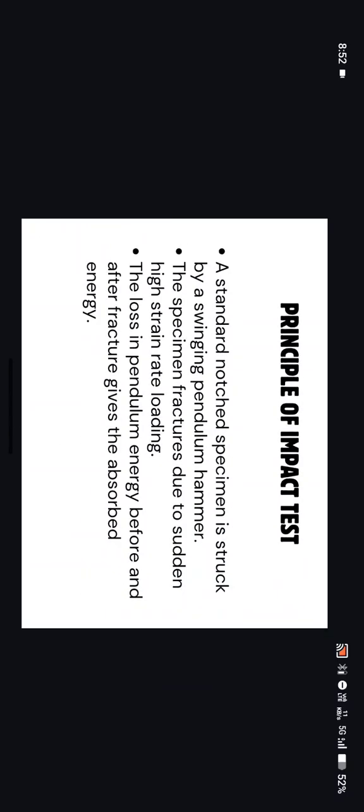Principle of impact testing. A standard notched specimen is struck by a swinging pendulum hammer. The specimen fractures due to sudden high strain rate loading. The loss in the pendulum energy before and after fracture gives the absorbed energy.